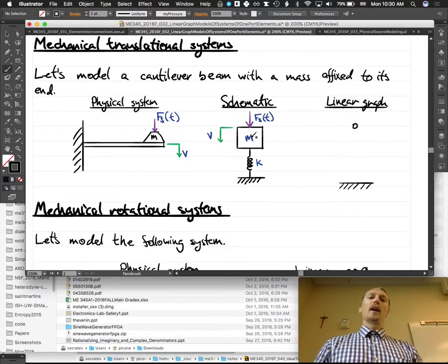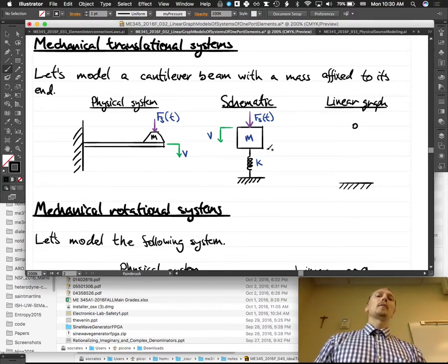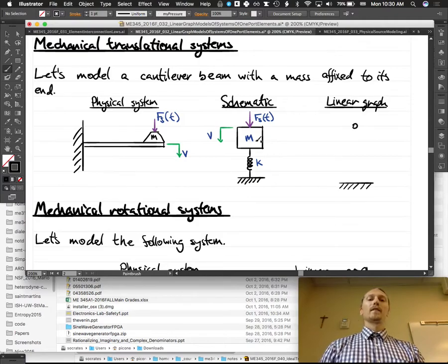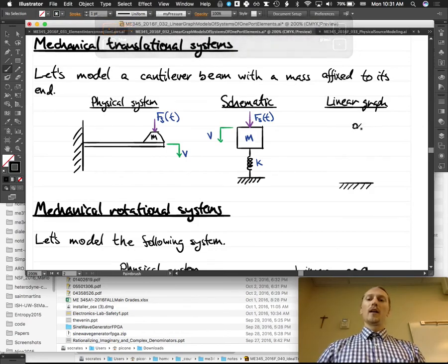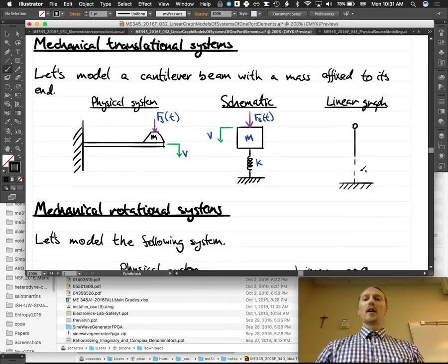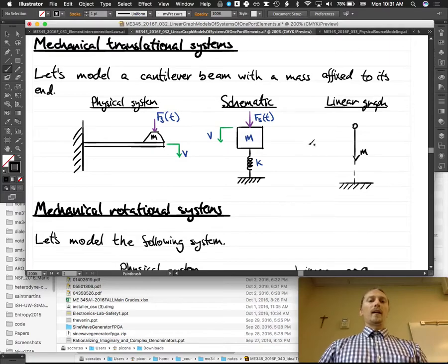Yeah, so for each lumped mass element we assign its own node, because it has a distinct velocity. So whenever we have a mass node, let's go ahead and draw the mass node going to ground, because it's always going to go to ground, right? There's M. We can also draw in, so where does the spring element show up? To the ground, yep. So it goes to the ground.